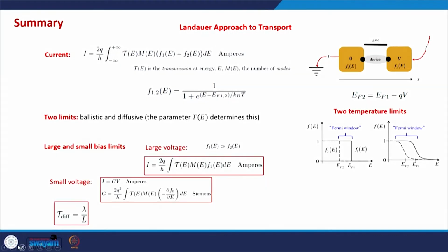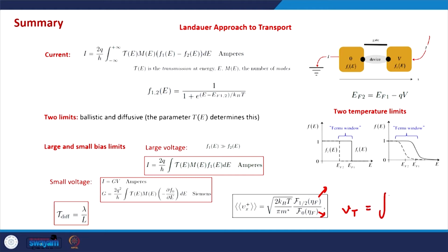by exponentials, and that is why we can cancel out the term in the numerator and the denominator, and that is why this thermal velocity is defined as unidirectional thermal velocity is just defined as this thing without the Fermi-Dirac integrals, because this is the velocity at equilibrium, which means we are assuming that the below threshold conditions are prevailing, and below threshold conditions are the conditions which are quite similar to the non-degenerate case conditions.